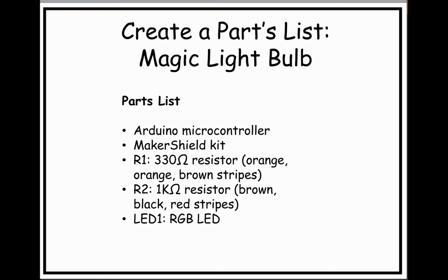There's also a little fourth color. It's gold, and the gold is just there to say, okay, based on temperature or current that's flowing through it, it might change that resistor value just a little bit. So we put a little window, which we call a tolerance. And as long as we're within the tolerance, in the case of these guys, it has a gold stripe, it'll be within plus or minus 5%. Okay? So the next resistor is a 1K ohm resistor.